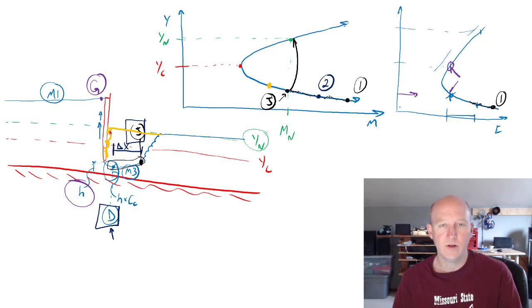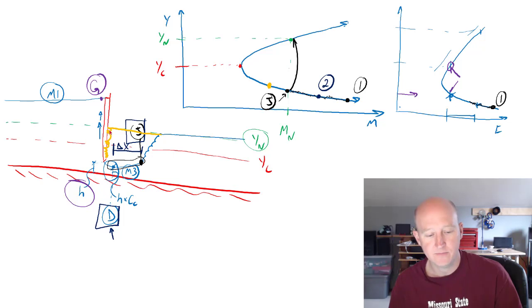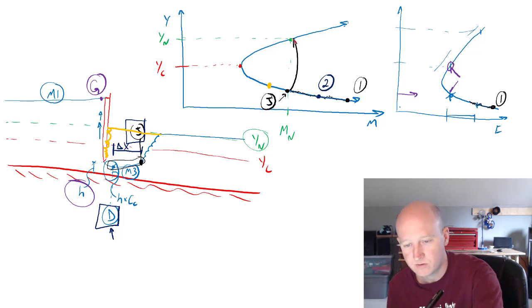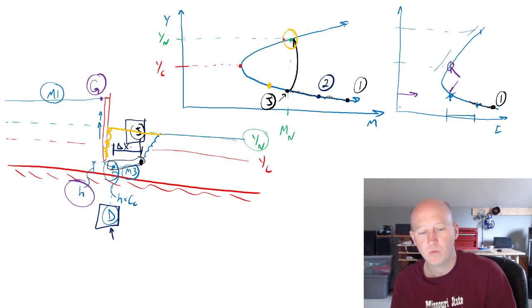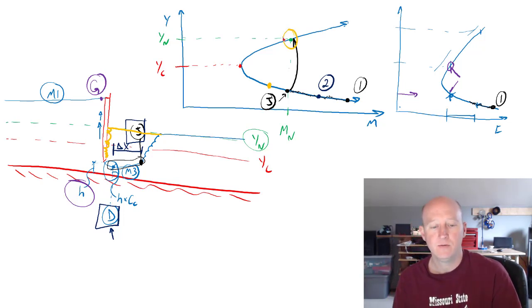And so when you do a calculation for a gate with a mild slope, what you need to do is at section D, just take a quick look and see what the momentum at D is. So if the gate's too high, the momentum at D will actually be less than the normal depth momentum. So here's the normal depth momentum. And so in that case, there's an incomplete hydraulic jump. Essentially, there's no delta X calculation to be had.